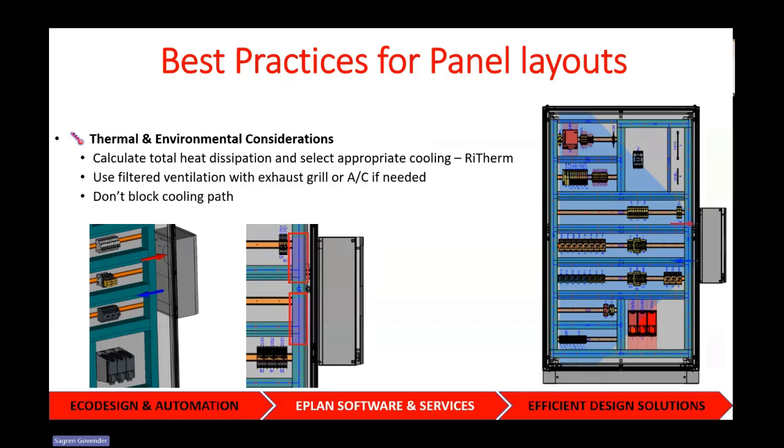Just make sure you don't block your cooling path. And again, EPLAN has some of these tools available in Pro Panel where you can actually see if your cooling paths are being blocked.